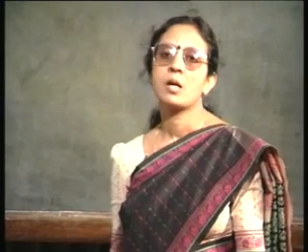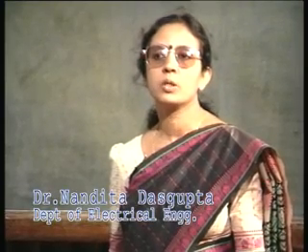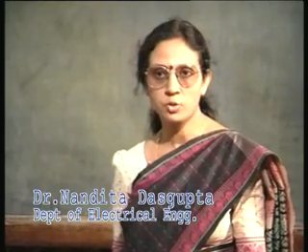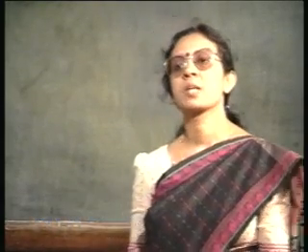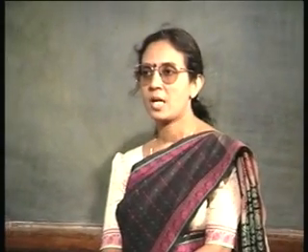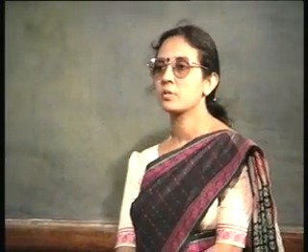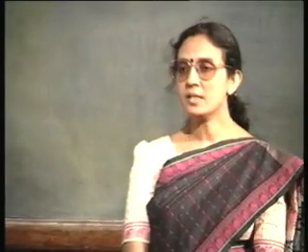Well, you know, diffusion is a high temperature process. The temperature ranges from say 800 degree centigrade to 1200 degree centigrade, and it is carried out in a fused quartz tube. Inside a fused quartz tube, we use a furnace, and inside, the silicon sample is placed in a quartz boat, and then it is exposed to the ambient in which the dopants are present.